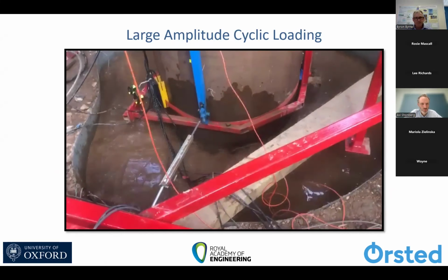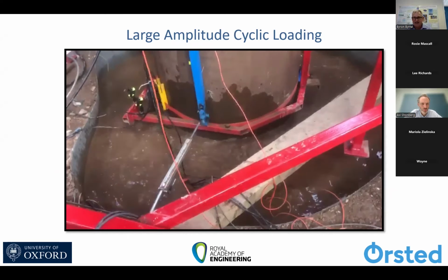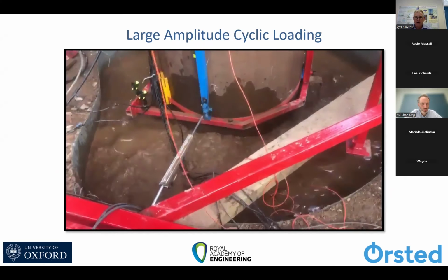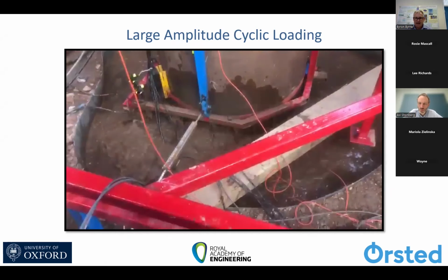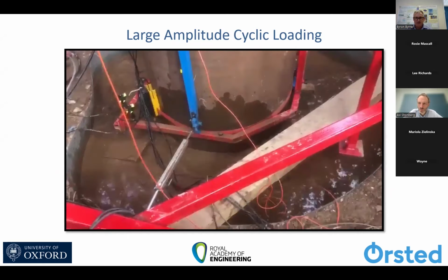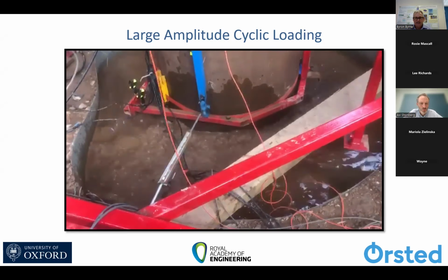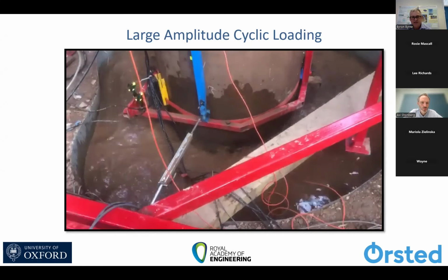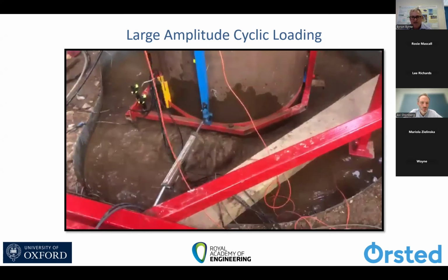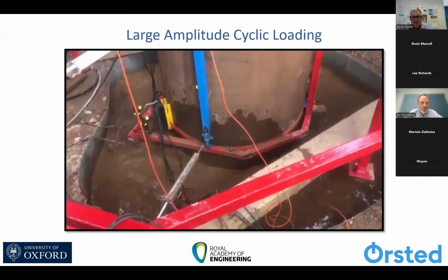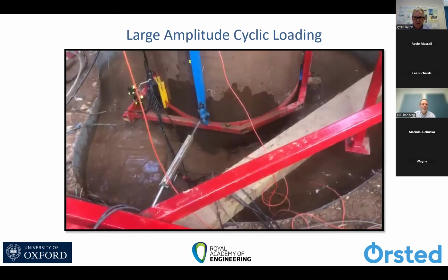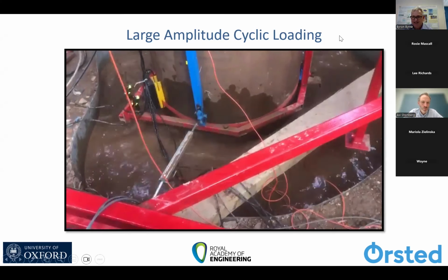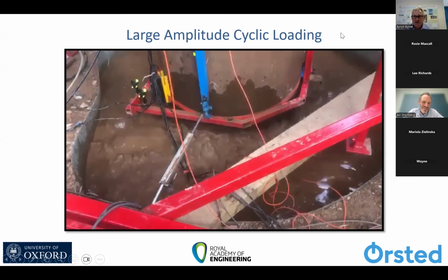Just to show one part of the testing, this is clearly at the end of the test where we're applying a very large amplitude displacement and load to the pile. Clearly, big gaps forming. We've got pumping of the water in the gap, and this is well past perhaps the serviceability of the pile if a structure was on top of this. But even at these displacements, the load capacity was still very significant. We could still mobilize loads consistent with the monotonic capacity. And you can see obviously the transducer here significantly affected by the water being pumped up onto it. It stopped working, I should say.